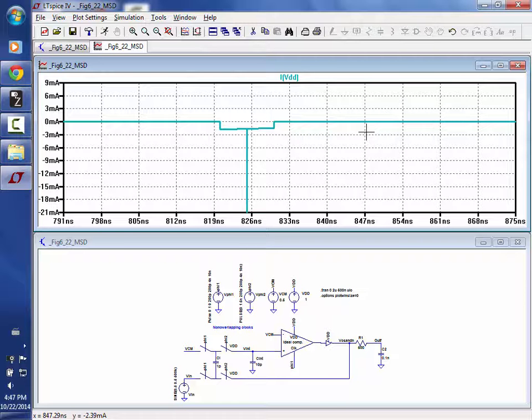So okay, does anybody know what's the simple way of thinking of RMS currents or voltages? What's the definition? You take a DC voltage or current and you put it on a resistor, and you calculate the power, and you get a power, right? VDC squared over R. For RMS, the way you calculate power is you take the RMS voltage, square it, and divide by the resistor, and it gives you the exact same power as an equivalent DC source. So the DC and the RMS are dissipating the same exact power.